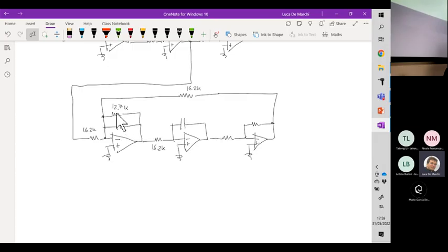That's the reason why this guy is less than this one. The capacitance is 2.2 nanofarad for this guy and this one. And 10 kilo and 10 kilo are needed for the inverting configuration. Okay? Last step.